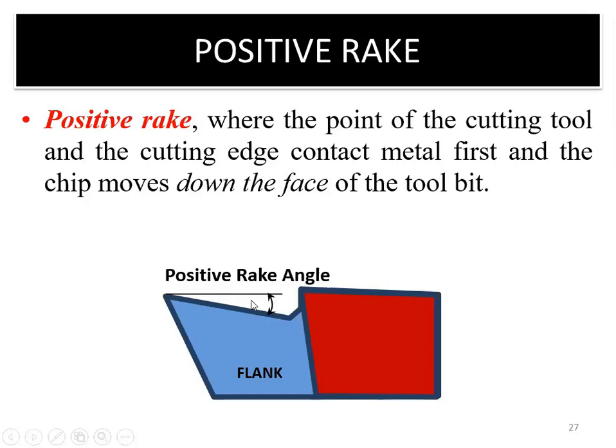Two sides, we have weakened it, so it may break, because hard material is going to give you discontinuous chips, meaning intermittent cutting, and this will give you jerks and can damage your tool easily.